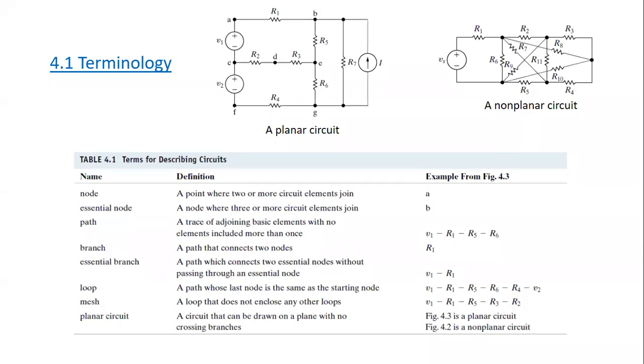For the nodal voltages technique that we already finished, it doesn't matter whether the circuit is planar or non-planar. The nodal voltage technique is suitable for all types of circuits. But for today's technique, the mesh analysis technique or mesh currents technique, we need to make sure that the circuit is planar. If the circuit is non-planar, we will not be able to apply the mesh current technique.